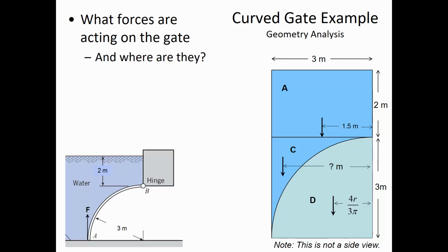So that's what I'm going to do in this next step. We've got this element B, which was 36 cubic meters. Let's weight it by volume. So 36 cubic meters is the weighting factor, and it should be located 1.5 meters from the edge if we're measuring from this right side.